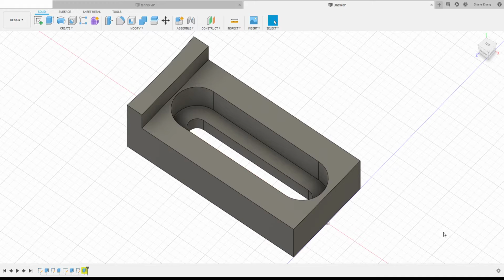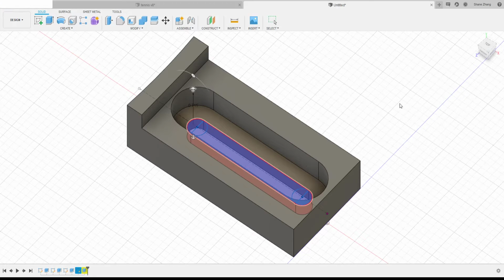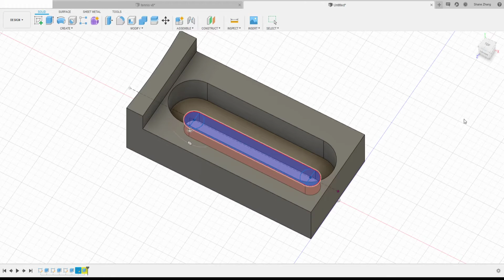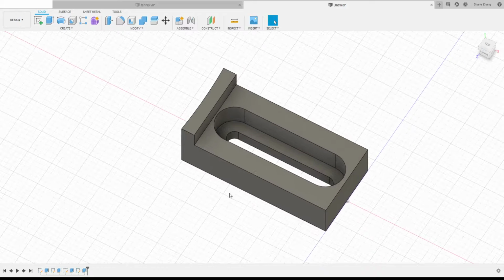And we still get a warning. So it still doesn't like you to extrude into nothing. Let's see if we can change the direction. Alright, so a flip. Simple. We'll just click the flip button and make the direction go downwards. And now it's happy. Alright, so these two slots are done.